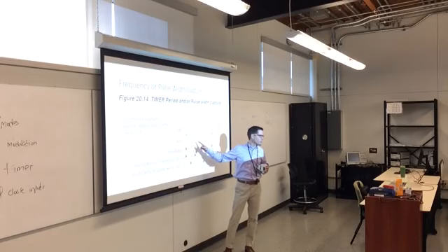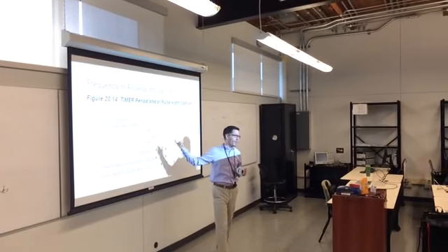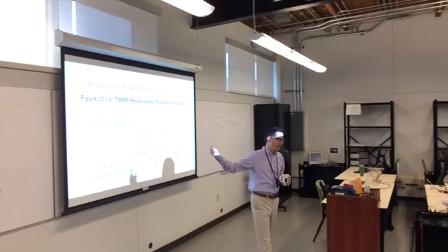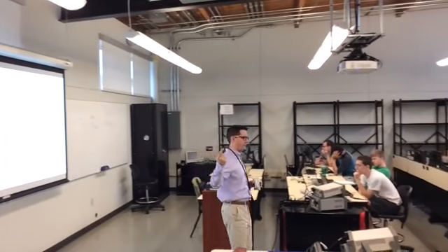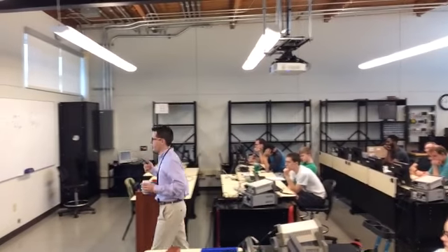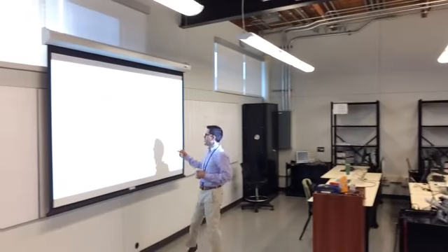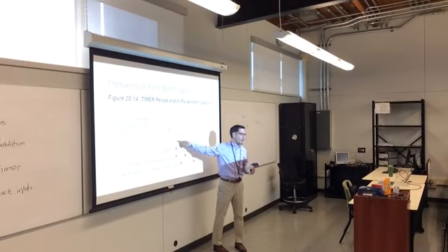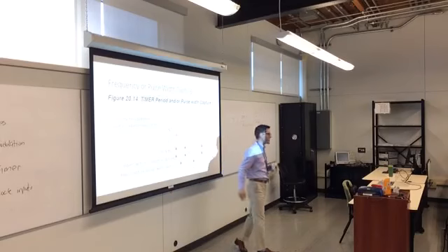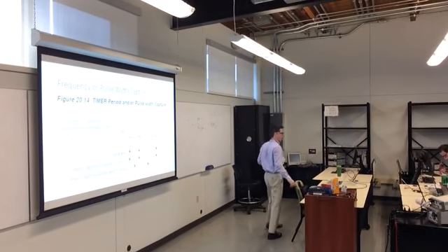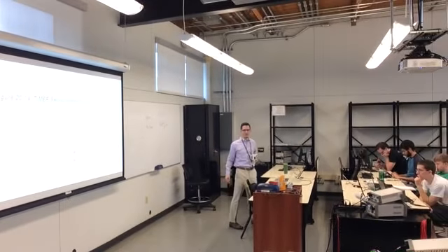So now you know the width of this pulse. If you wanted to know the amount of time it was high and the amount of time it was low, you would trigger on both the rising edge and the falling edge, and you could time all of those values and see how long it was high, how long it was low, and measure the duty cycle.